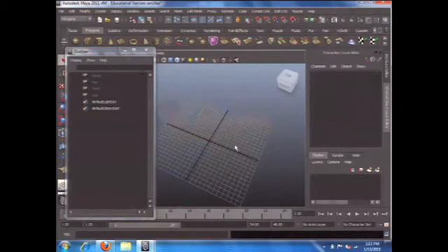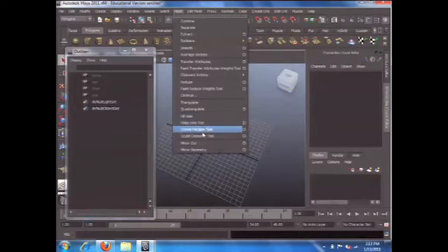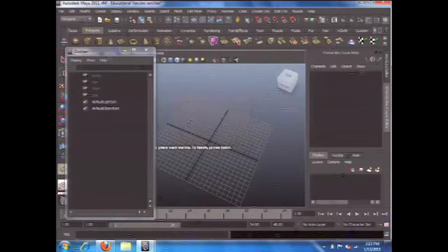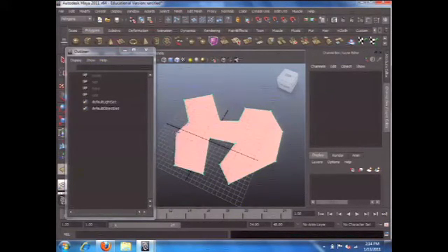I want to repeat one more time, in this create polygon tool, it's very similar to AutoCAD or SketchUp. You're just tracing the polylines. However, in Maya, if you hold Control, you can actually click a point inside, release Control, and if you keep drawing, you can create openings inside.